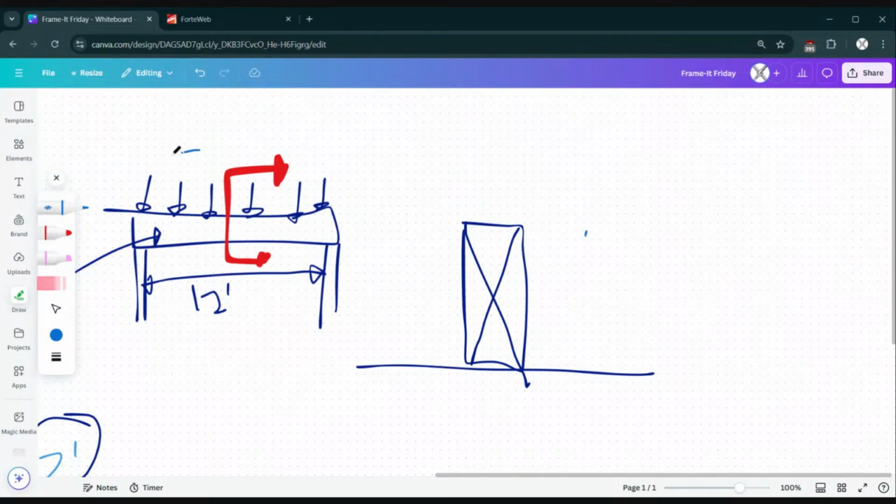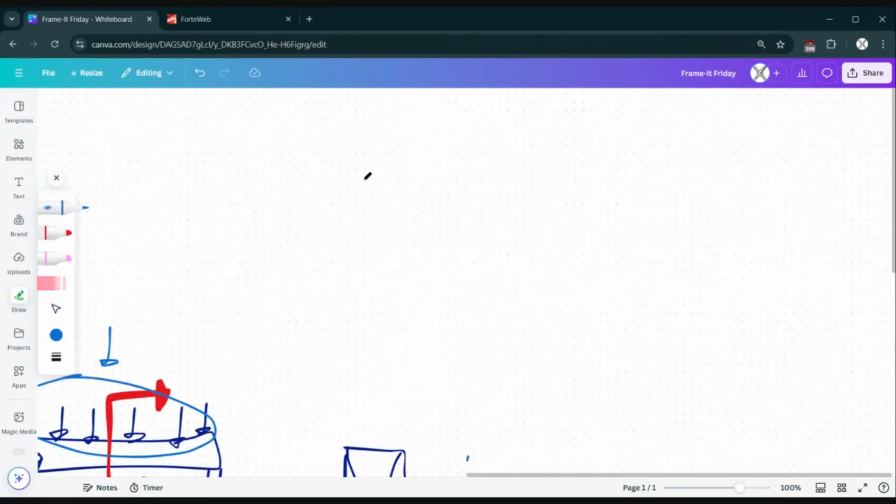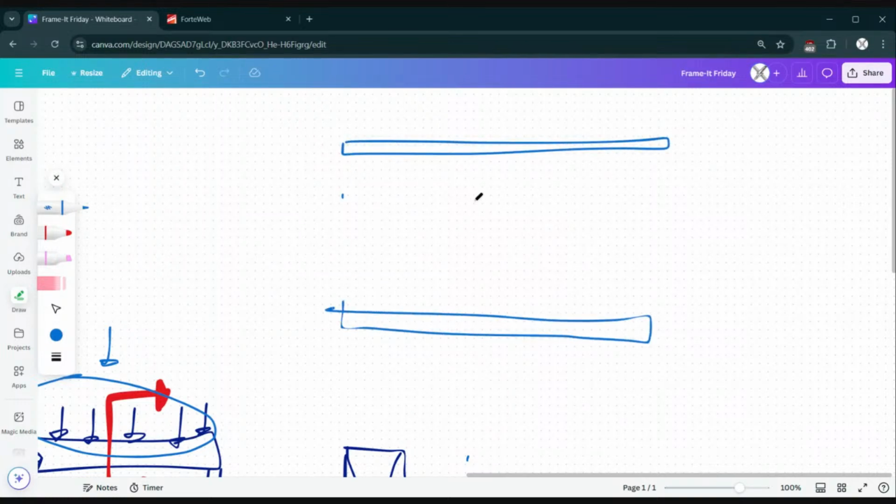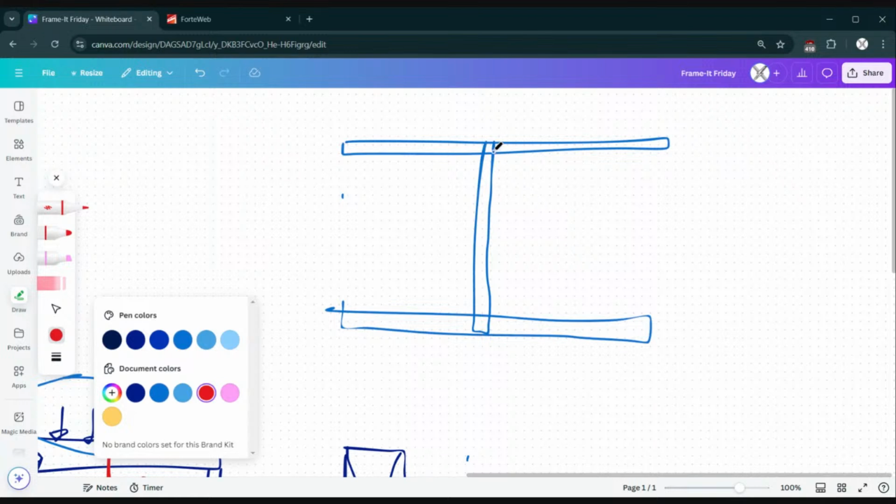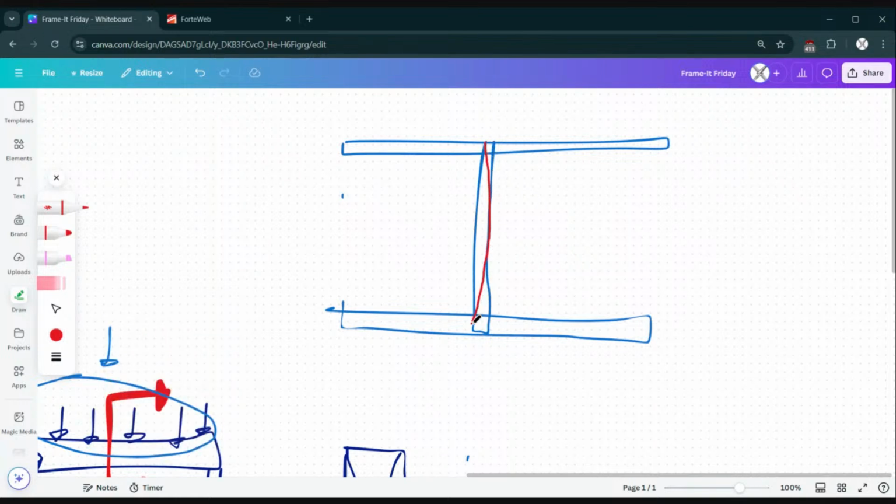When you put a bunch of weight on top of a beam, the first way it actually fails is the top of the beam will try to bow. So if we look top down on this scenario, it would look something like this. We have a wall and we have a wall over here and the beam goes straight across. Everything's nice and happy. And if you load this beam super duper heavy, the first way it's going to fail is actually going to be by bowing. And it would do something like this. The top of the beam is going to deflect and fail in a column sense.